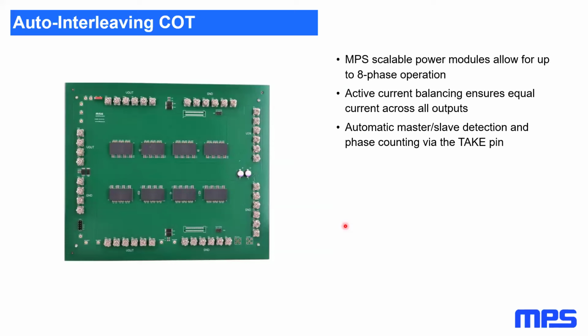But many of you have worked, I imagine, with multi-phase converters in the past, so you know that the advantages of using multi-phase converters is that we can deliver energy much faster to our load, and we can also reduce the output ripple significantly. However, it also entails certain added complexity to our design, first of all making sure that we are properly operating in multi-phase, distributing the phase differences equally amongst the different converters, as well as balancing the output current.